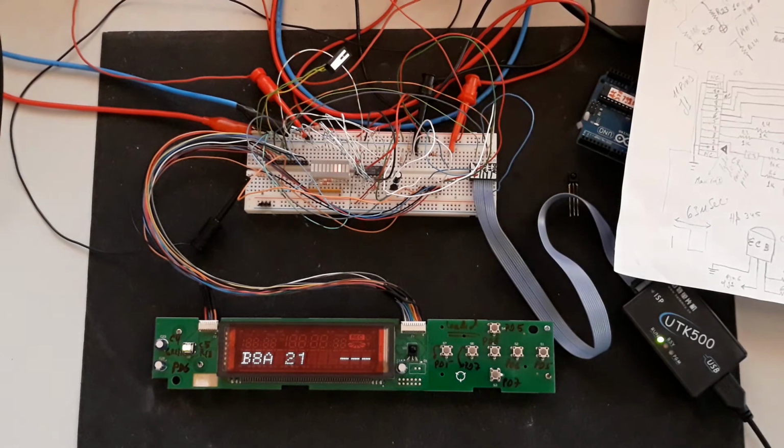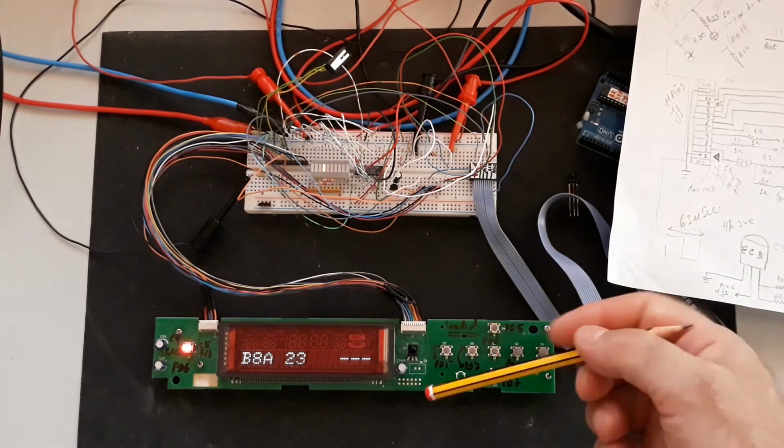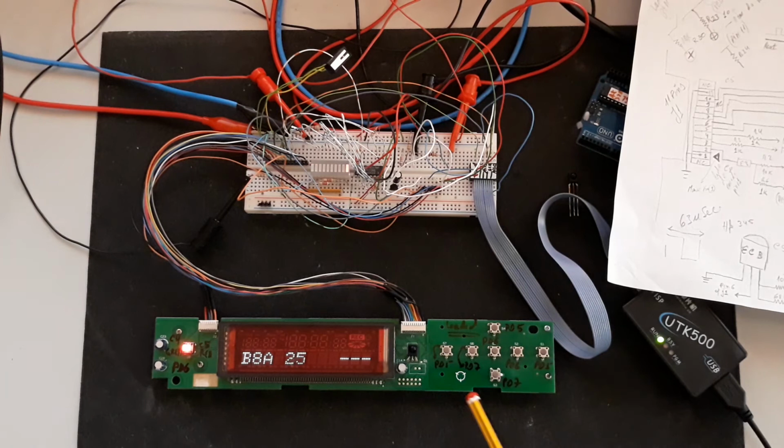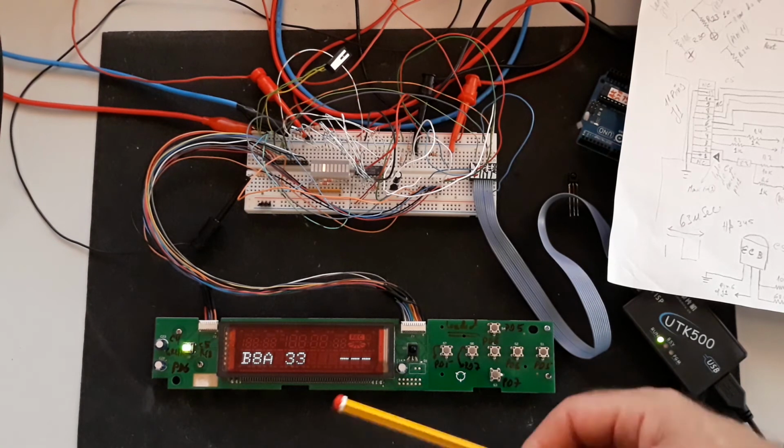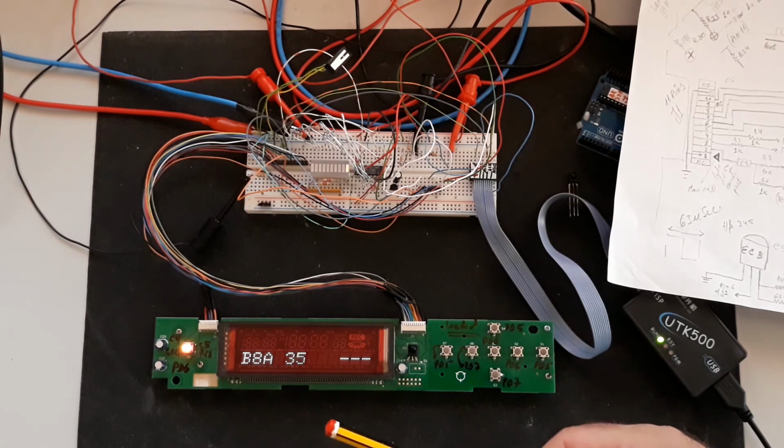It happens because in the communication protocol I'm using, I have the toggle bit, the third bit, and this bit changes when you press the same button, but does not change when you keep the button pressed, okay? You need to study the protocol to understand what's happening here.